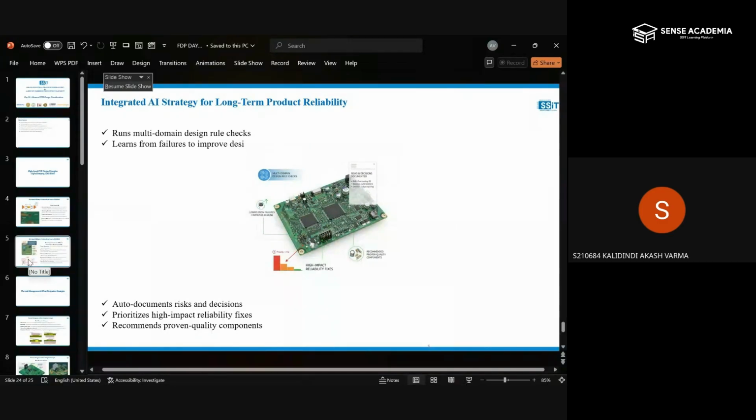So we needed to bring the PCB. We needed to check whether heat is generating, with heat guns. While running the particular PCB, we would take a heat gun and check what the temperature is. If there is high temperature generation, then we would think about making the copper pour higher, or taking care of thermal vias, or else any liquid material, metal material, or vapor chamber tubes. What mechanism should we go for? Once we received the PCB, we would think about the particular mechanism.